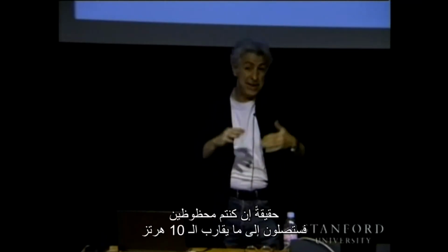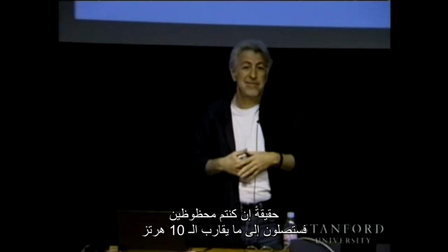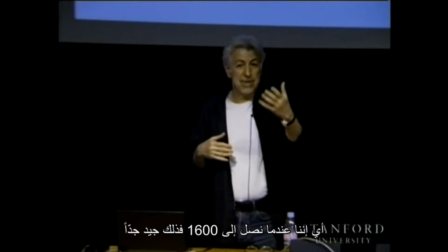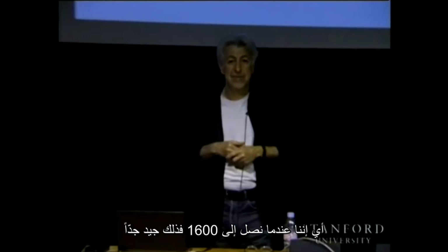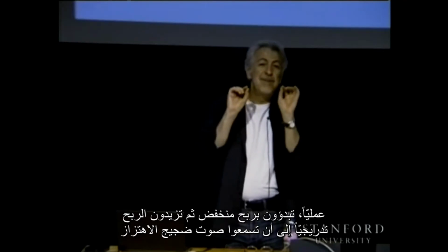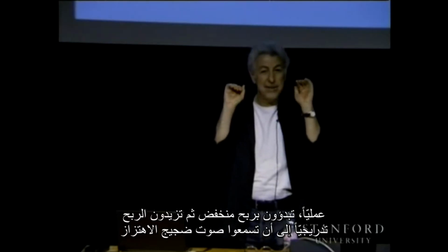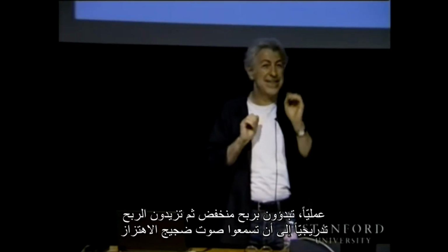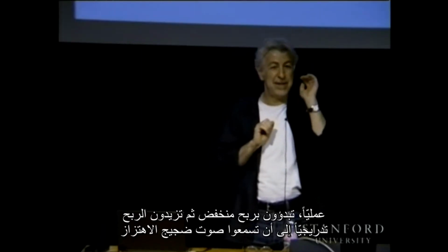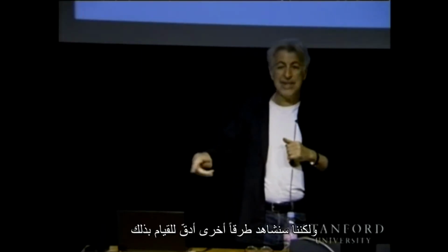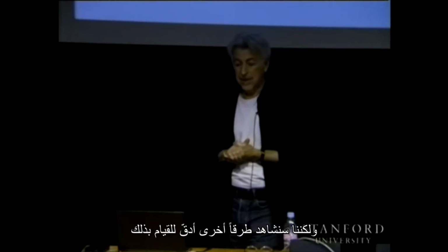In fact, if you're lucky, you can go to 10 hertz. I mean, this would be great. So when we go to 1600, this is really nice. 40 divided by 6. Well, in practice, you start with very low gains, and you start tuning your gains up, and suddenly you're going to hit that noise, start to vibrate, so go down. But we will see some ways of doing this in a more precise way.